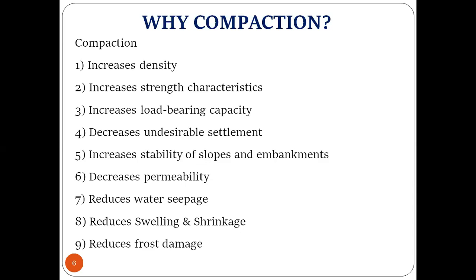And it decreases permeability. When there are fewer voids, it is denser, means what? There are fewer voids, right? So when there are fewer voids, it will not take water into it, so the permeability also decreases. And it reduces water seepage. When water cannot pass into the soil, then water seepage will not be there. So it reduces swelling and shrinkage.